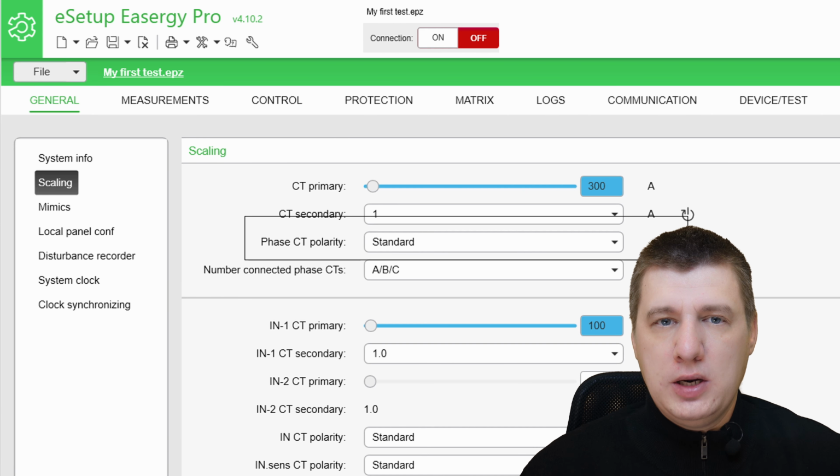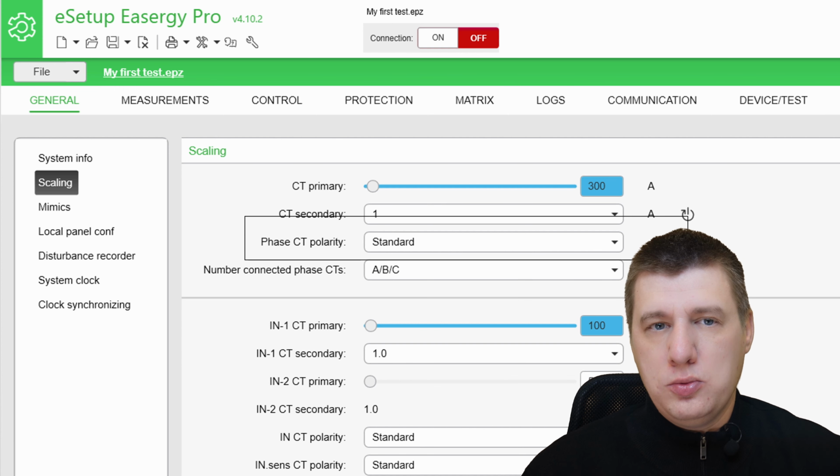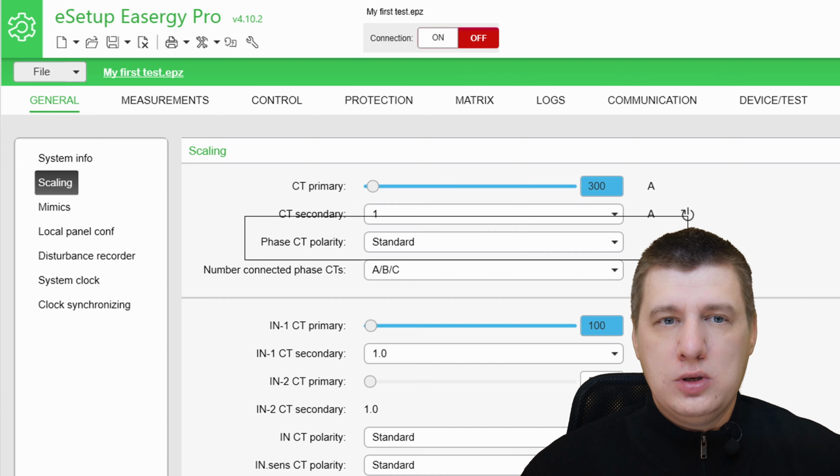Physical wiring and identification. CTs are marked with the primary terminals, typically P1 and P2, and secondary terminals S1 and S2. On the P5, secondary CT wires are connected to the analog modules in slot A, specifically terminals A9 through A18. If the secondary wires S1 and S2 are swapped at the relay terminals, the measured current phase will be shifted by exactly 180 degrees.